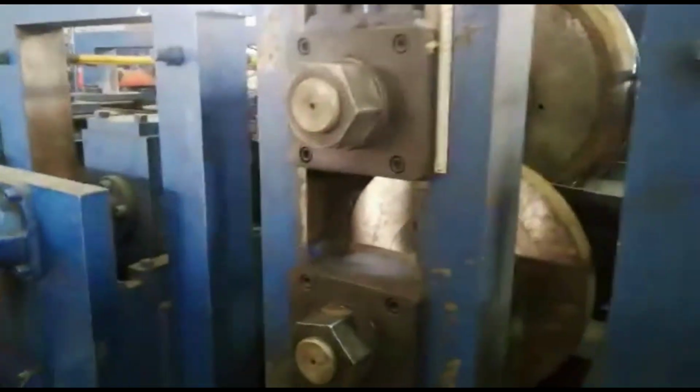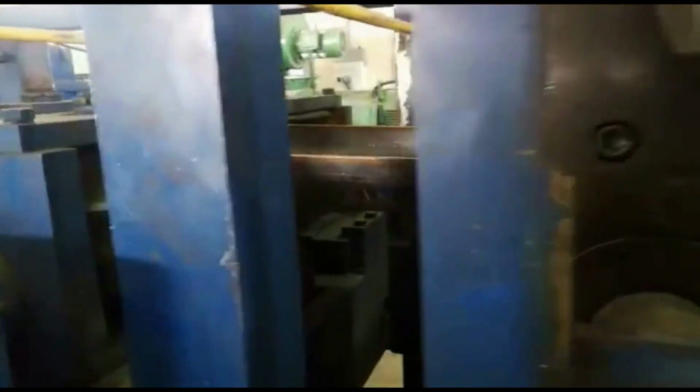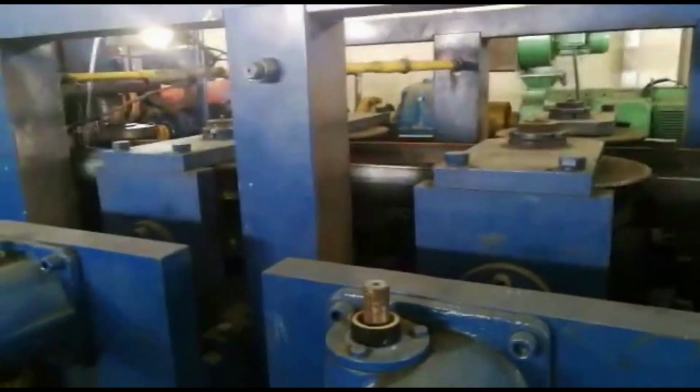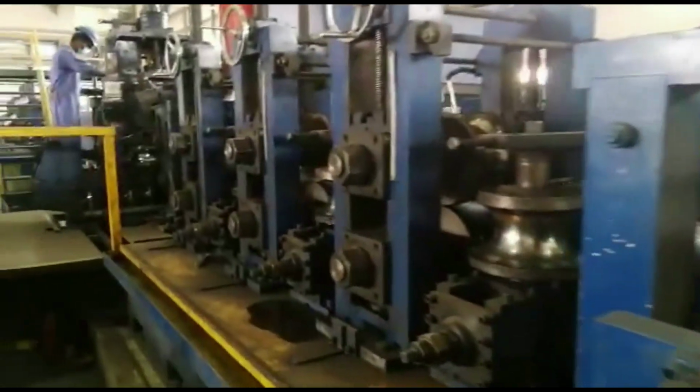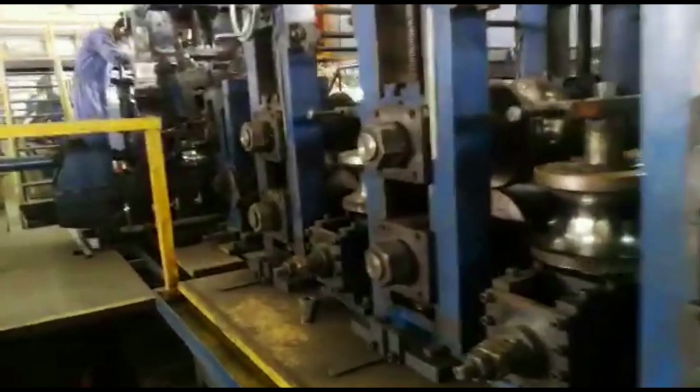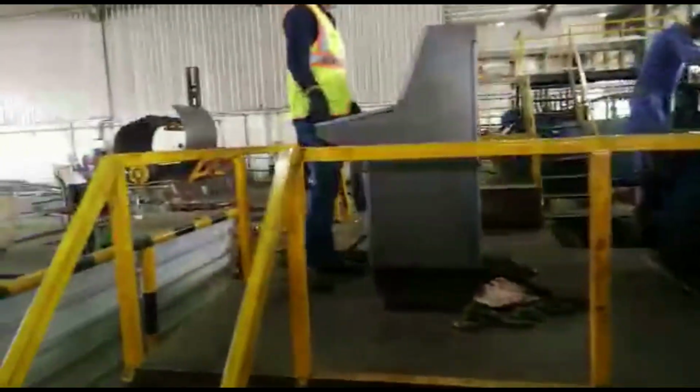The actual process of pipe manufacturing starts from here. From overturning rollers it comes to rough forming machine -1, where pre-bending and gradual bending takes place. Vertical roll group gives curvature to the bent flatbar. Then it comes to the finish forming machine, where finishing and preparation of edges take place before welding.